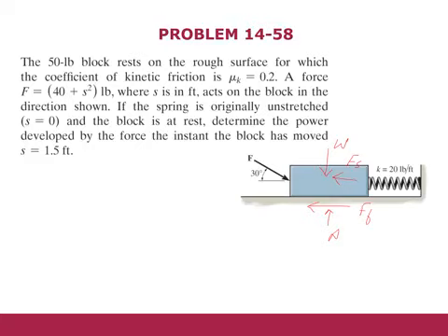These are the forces which are acting on our particle. In order to calculate the work done, we will use the work energy principle, which is the sum of all the work from 1 to 2 is equal to T2. We have covered the initial and final kinetic energy. We are working on the work done by the forces. First, let's take this force F, and we will take only the component in the direction of the displacement.